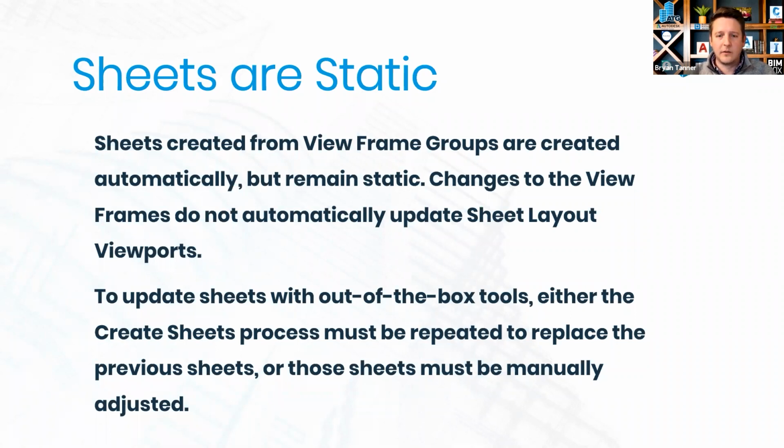with our clients. So we either have to manually make those changes to the individual layouts and the individual viewports so that we save all the changes that we've made in those sheets, or we have to wipe out whatever progress that we've had and recut the sheets using the out-of-the-box tools from Civil 3D. It's just inherent to the programming of Civil 3D. The thought process was, and remains to be, for the programming of Civil 3D that the last thing you do on a project is cut sheets.